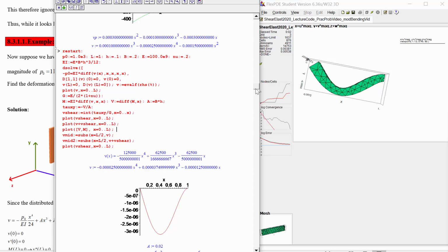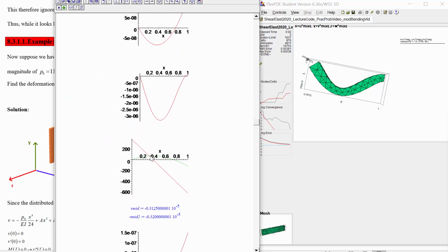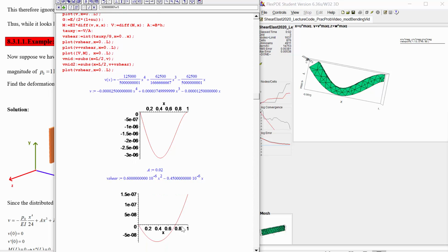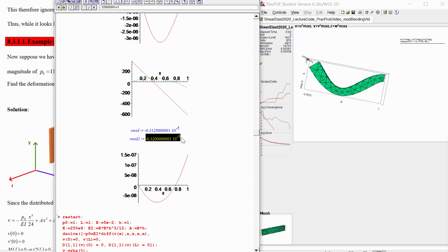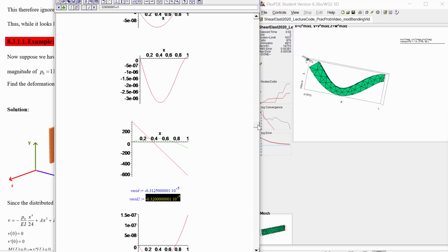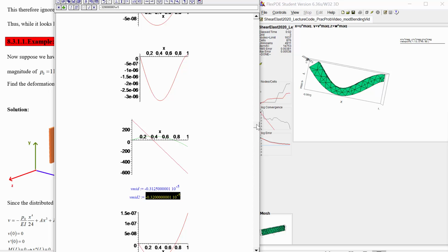But we're just going to deal with this as a limit of the current more approximate approach of figuring out what scale the shear deformation should be about and what scale the bending deformation should be if it's the only thing that is there. And sometimes it's going to be valid to add those by superposition and get something closer to what's going on in FlexPDE.